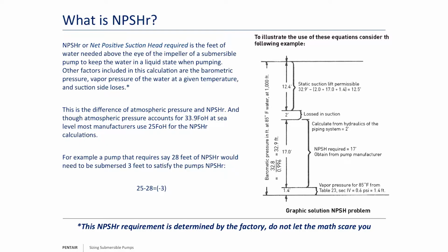Now, I'm a conservative guy. I say the magic number is 25 feet. 25 feet of head is given to us by the atmosphere. And why I pick 25 is because I'm a little conservative. I've heard some people teach 27, and that's fine.